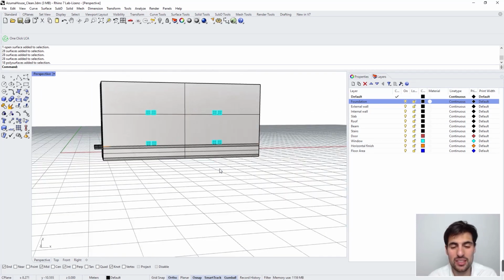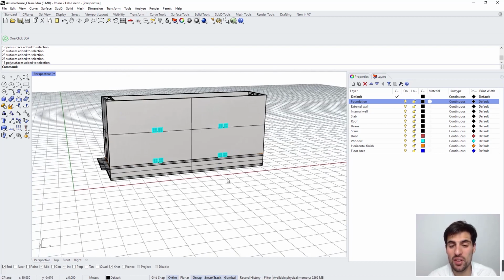level because this was actually part of the building, but it wasn't modeled in the original model, so you have to check out for those details that perhaps weren't important in the design phase, let's say, for the architects or other planners, but of course they are very relevant for the life cycle assessment. So check out if there are some parts of your building that you have to add to the 3D model.